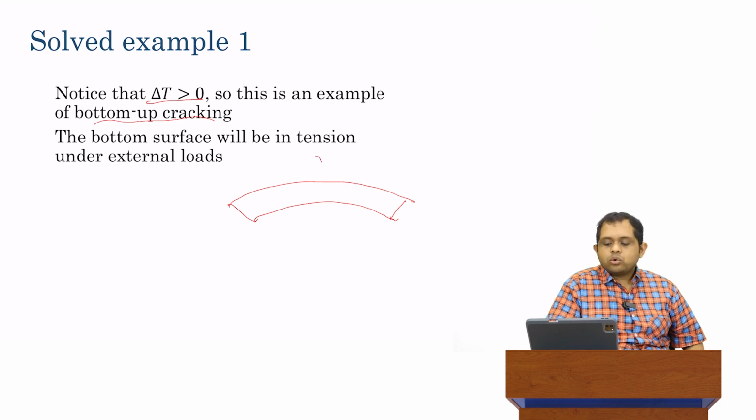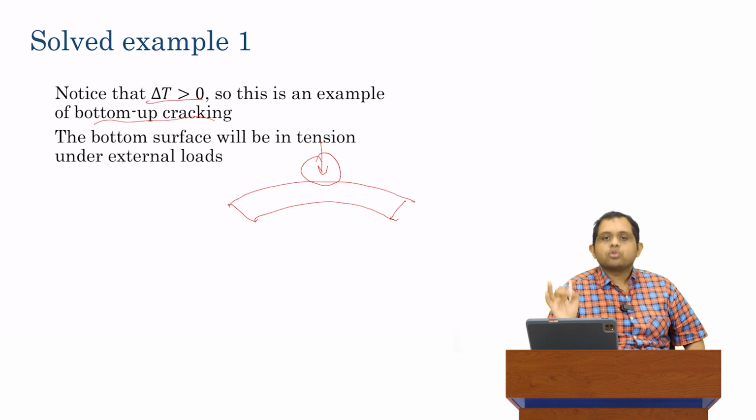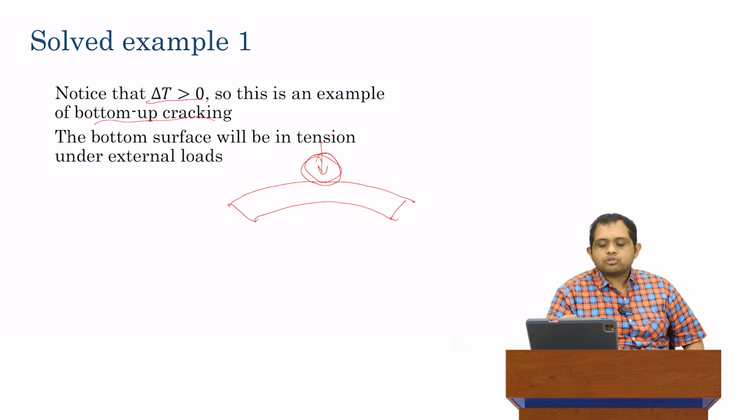So if I apply a load over here, the constant component is basically not causing any stress because we assume that the base friction is negligible. So push that aside. But if we consider curling, and the pavement is trying to assume this sort of shape, again, this is not the actual shape of the pavement. It's the shape that the pavement is trying to assume. It is going to be restrained, of course, by the self weight, but also by an external load which may be applied over here, as I've shown.